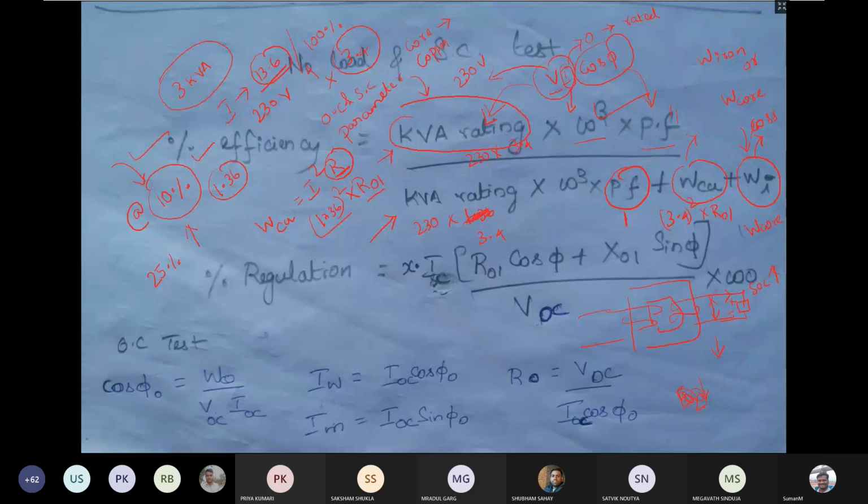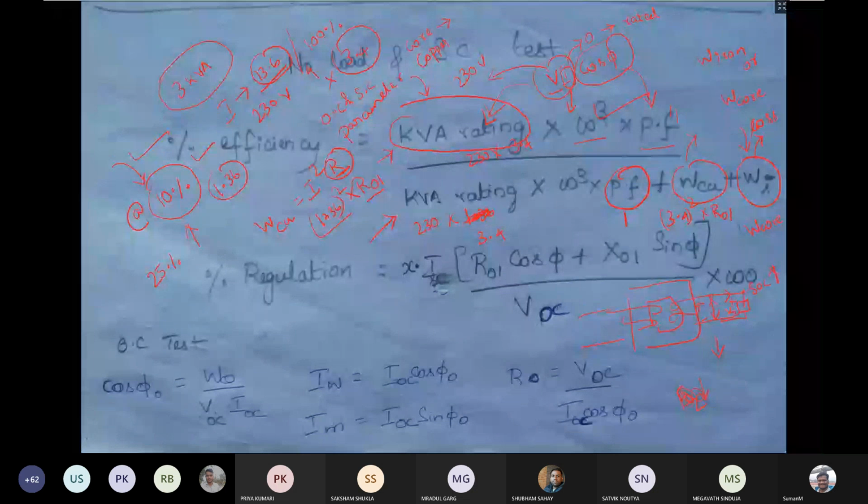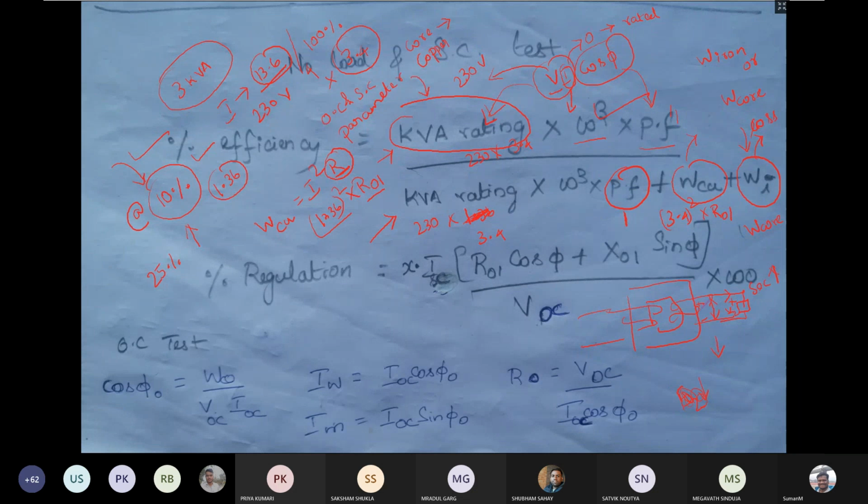Why is it decreasing? Because the copper loss is increasing from no load to full load. When the copper loss increases, the voltage across this load decreases. The induced EMF will also decrease, because there is some copper loss on the primary side. Also, the voltage across the secondary terminals will decrease. Now, if I add X amount of load, then some amount of voltage is going to decrease.